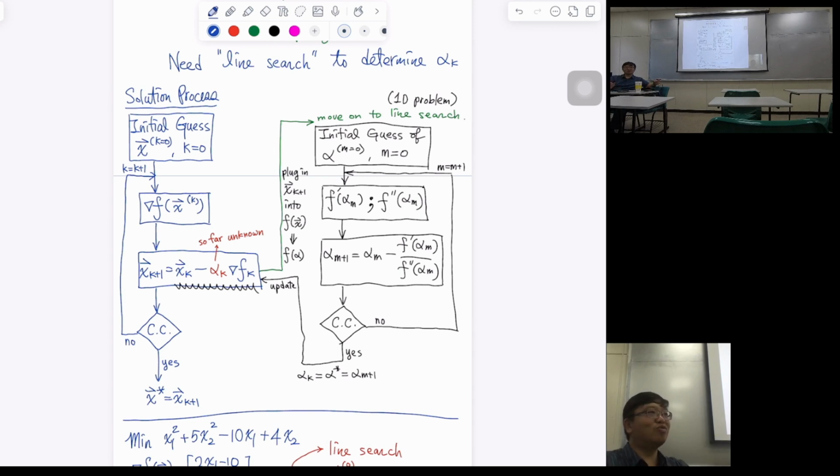Like, once you design a motorcycle and you realize it's too heavy, you need to reduce the weight. Then your objective function becomes minimizing total weight. But as an engineer or the company, you still need to satisfy certain design criteria, such as the strength of this cylindrical bar has to be stronger than something.